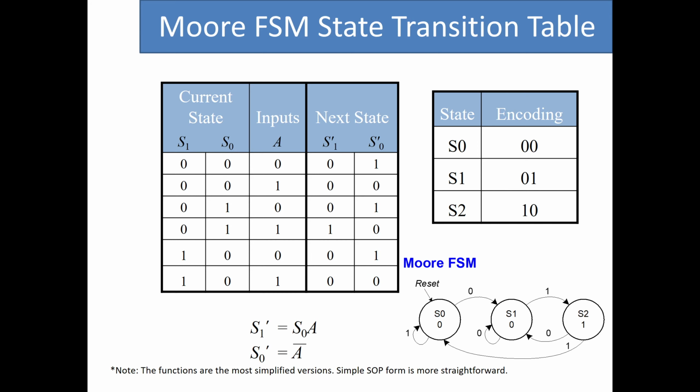So if we do that, these are the most simplified sets of equations. So I highly suggest you do it on your own. You create the Karnaugh map for 3 variables, S1, S0, and A, and you fill out that table, and if you look closely, you see that using 3 variables, we can have 8 possible combinations.